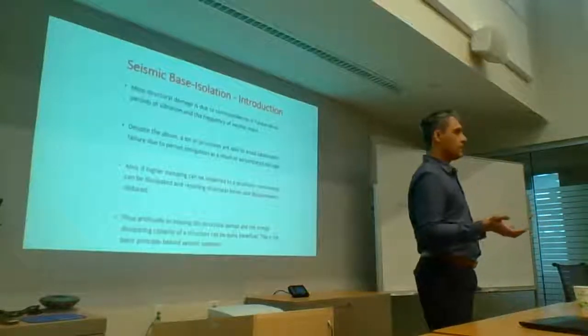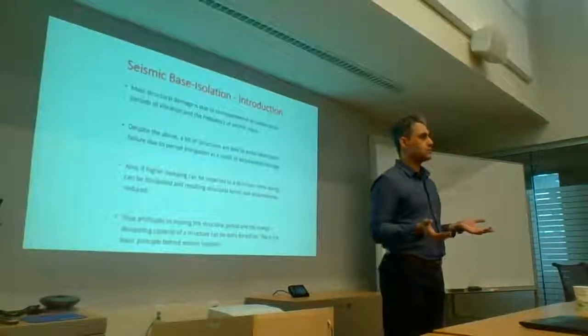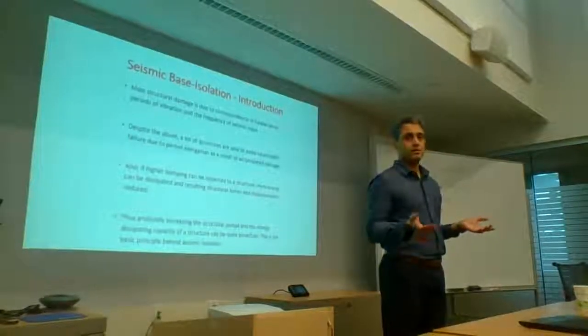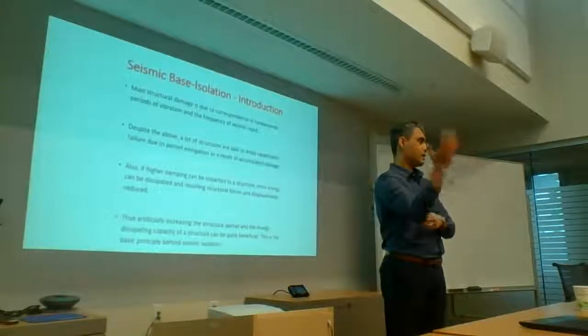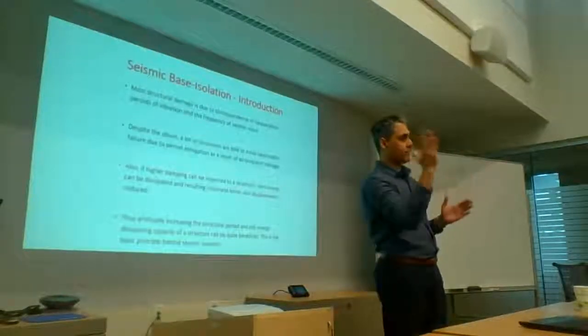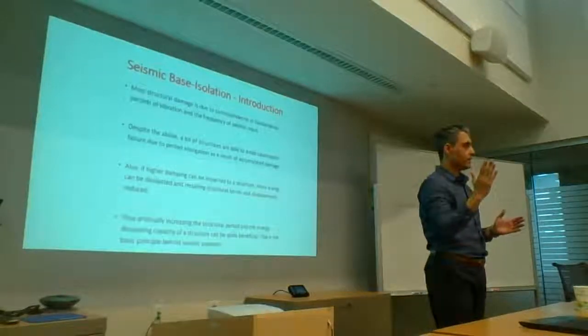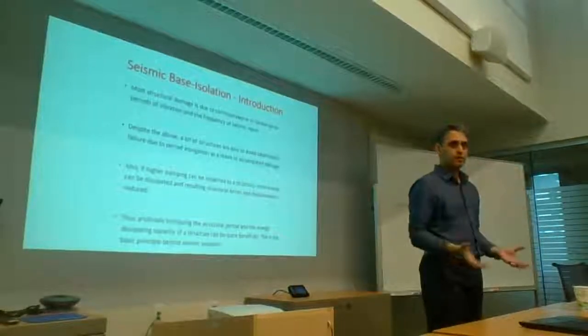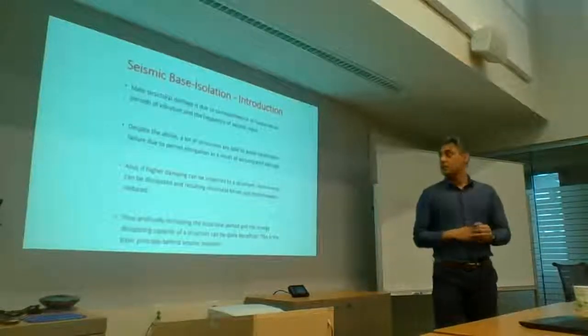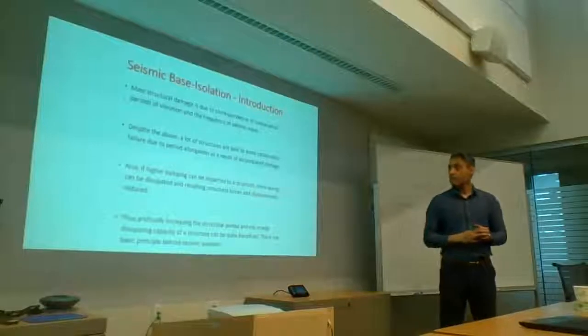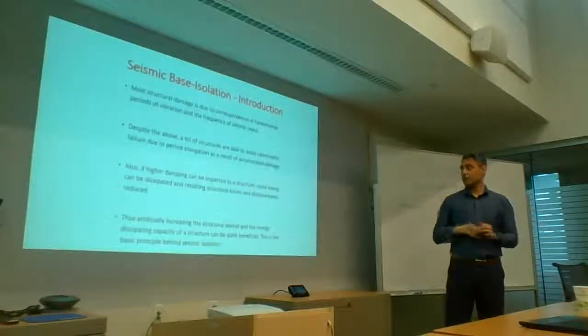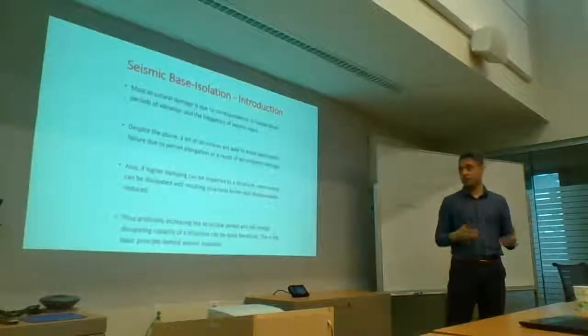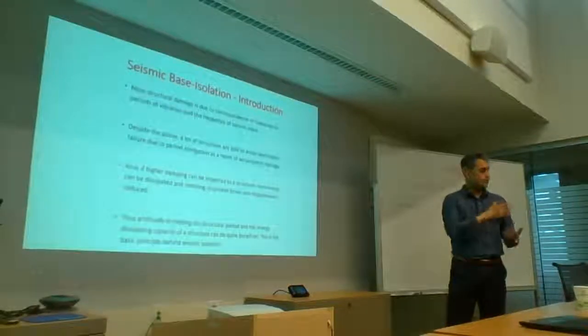Now the 20 to 30 story buildings were what had some real damage, because there was resonance. There was that correspondence between the fundamental period of a 20, 30 story building and the energy that was coming through the basin.